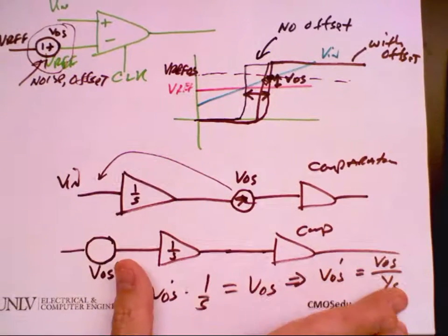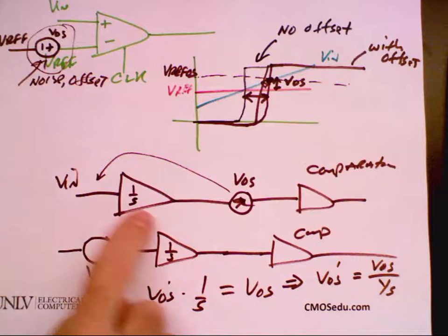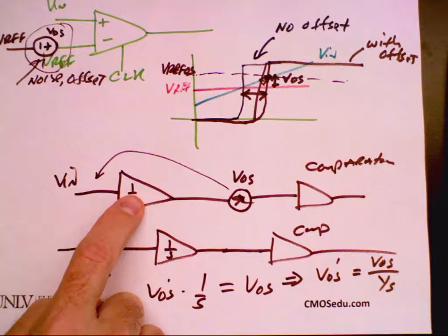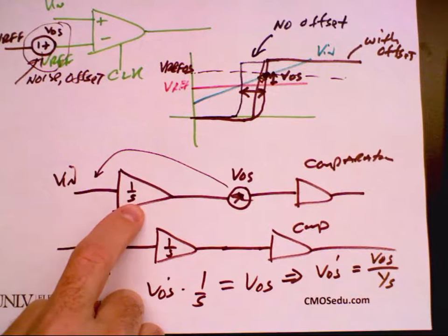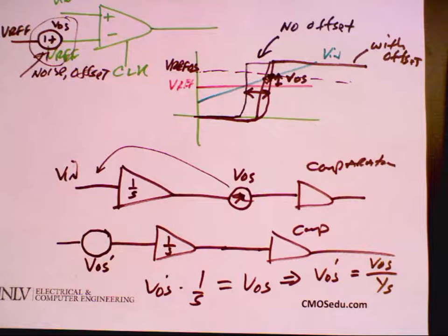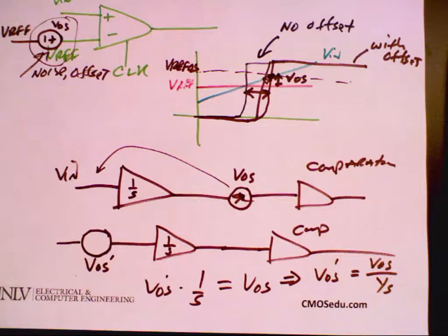Okay, so I got a question. Does anybody have any questions on that before I ask my question? Okay, what if I have offset or noise? I won't have hysteresis because that's not a digital circuit. Here with this integrator, what happens to it in the input signal? The input referred offset of the op amp, because the op amp's not going to perfectly be switching it plus and minus right there.